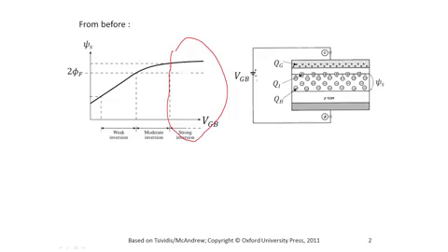So in this part, what is the most important characteristic as far as the surface potential goes? It is that the surface potential is almost flat, almost constant. It is not 2φF as you very often see in some books. It is 2φF plus a certain amount Δφ, which is significant. Actually, this is a realistic plot. So if 2φF is, let's say, 7/10 of 1 volt, Δφ here can be 2 or 3/10 of 1 volt.